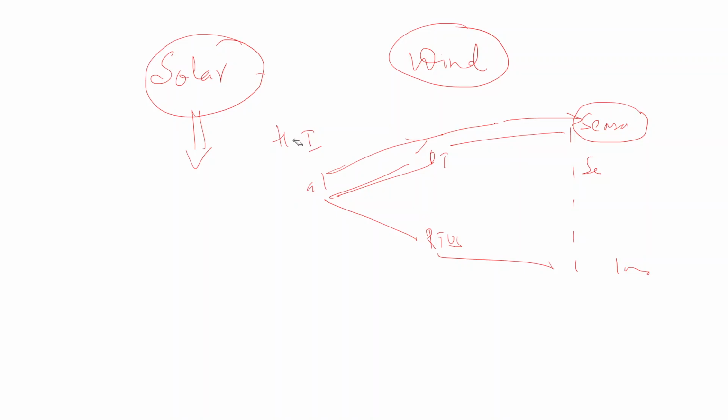And these IEDs communicate with the distribution control system based on their data. The DA control system collects the data from IEDs on one or more feeders, and then forwards the data toward the master. Based on the data, the operator will take a decision, whatever contingency he needs. If there is normal operation, there is no need to do anything. So, IEDs cannot directly communicate with the master station? No. A data concentrator will collect the data from IEDs installed on one or more feeders and forward the data toward the data master.